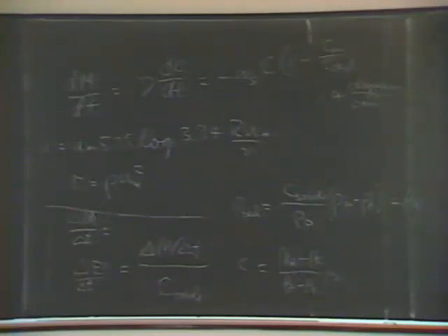As I've pointed out already, the tidal hydraulics vary region by region too, because of differences in resonances, range of the tides, and difference in freshwater outflows. Those are big factors. If you have a wide tide range, say a 10-meter range in the tide, 30 feet tide range, you can bet that there's going to be a lot of back and forth motion inside the estuary.